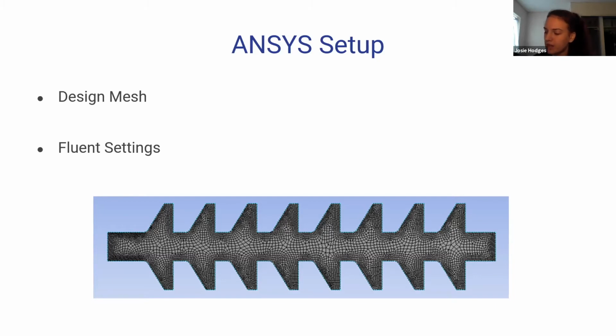For the actual simulations, I needed a time step of around 4,000 with a step size of 0.0001. It was trial and error getting these numbers, and it was just the number of times it iterated upon the calculations. I tested each injector in the forward and reverse directions, which you can see would be from one direction and then the other in this design. This is the mesh here, which was set up for the actual calculations.